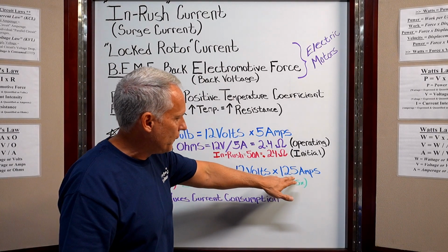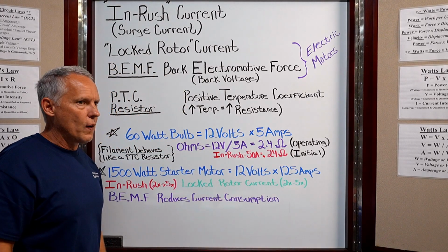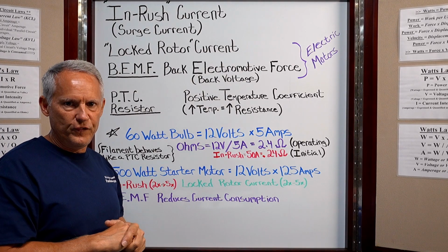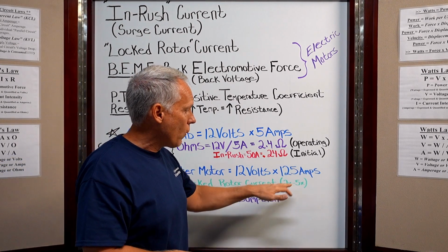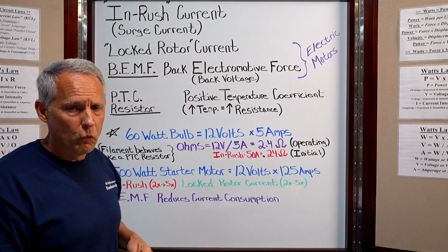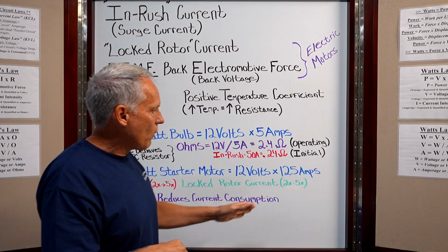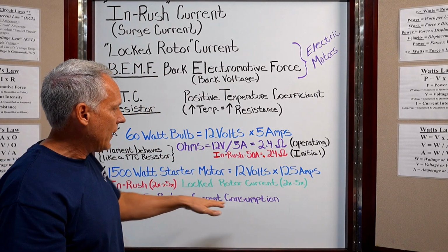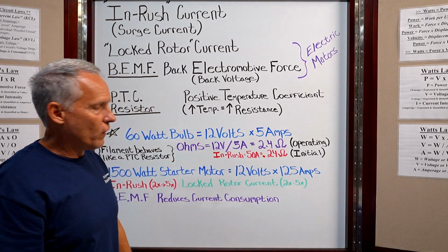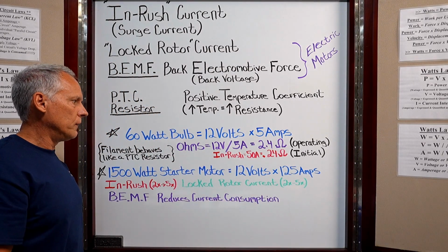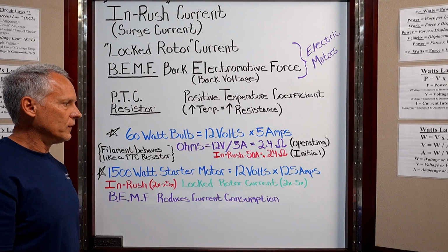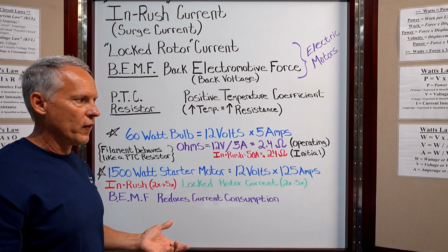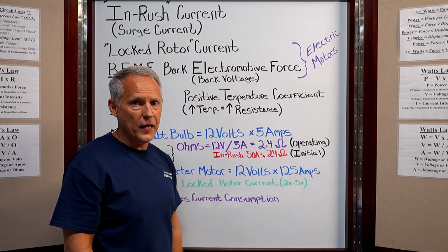So for example, if you said to yourself, well, 125 amps of current flow, I probably could get away with a 2-gauge wire. That should be more than sufficient. In reality, you may actually need a 1-gauge wire or even a 1-aught wire, which just gets larger and larger, depending on the distance of the wire, how long the wire is going to be. But you may find that designing that circuit for 125 amps is going to be drastically insufficient. You're going to have to be considerably larger as far as wire gauge. The protection for that circuit, whether it be a fuse or a circuit breaker or whatever, is going to have to be a lot greater than 125 amps.